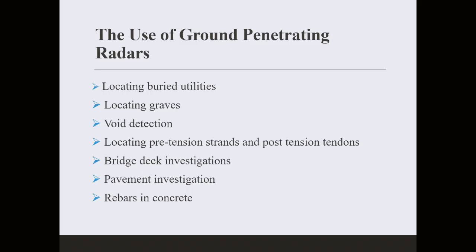So basically, this one is a sound or a radar wave, actually. It is emitted by a device. It could be a handheld device. It could be on top of a drone. It could be pulled by a dolly, or it could be attached to a truck. It depends how big the size of this device is. Through the penetration of radar waves, it could go up to a couple hundred meters. So it can tell you what's going on under any surface.